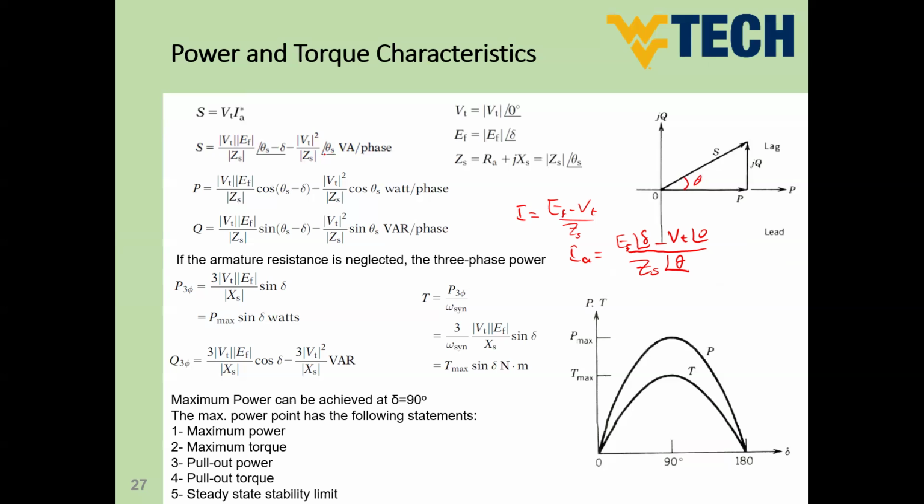So this is the apparent power vector in volt ampere per phase. If it is for 3 phases, guys, we have to multiply times 3 if these values are phase values, and root 3 if it is line values, in case of Y connection. Okay, guys? So this is a per phase apparent power.